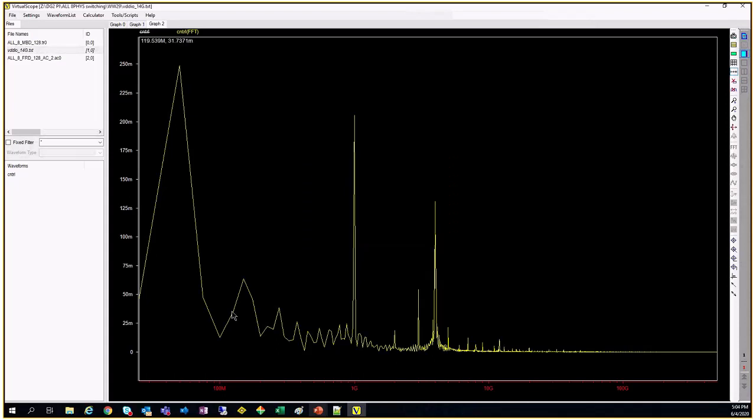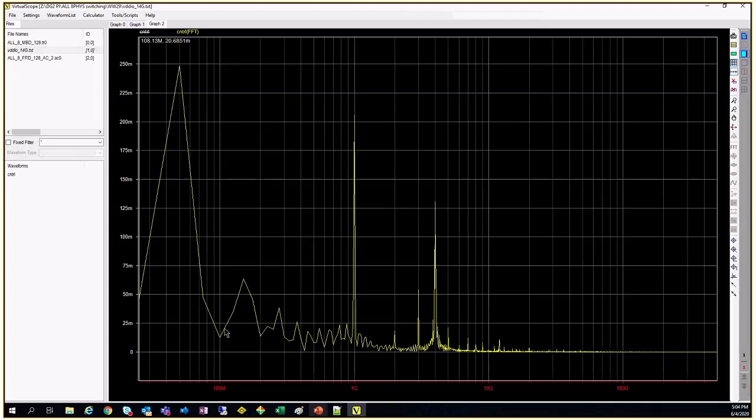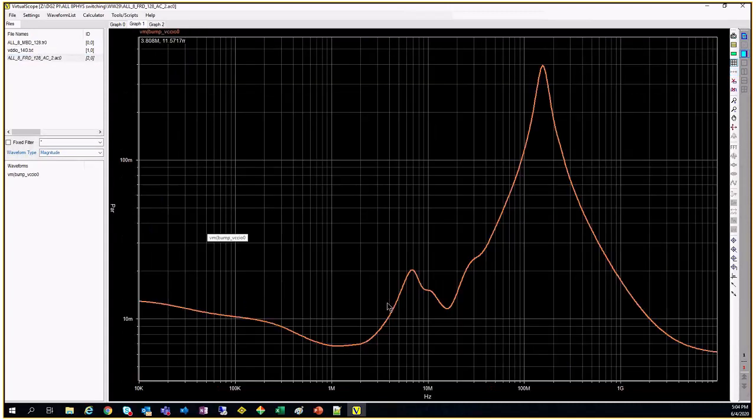So forget the starting part, okay? So if you notice here, right? So if you notice your current for different frequencies, right? For different, let's start from 100 mega, okay? So for different frequencies, your current has different amplitudes. That is the amount of maximum amplitude seen in different frequencies. So at the same time, your impedance also has different values at different frequencies. So basically, when you multiply your current into your impedance, you get your voltage drop, which you're seeing over here, right?